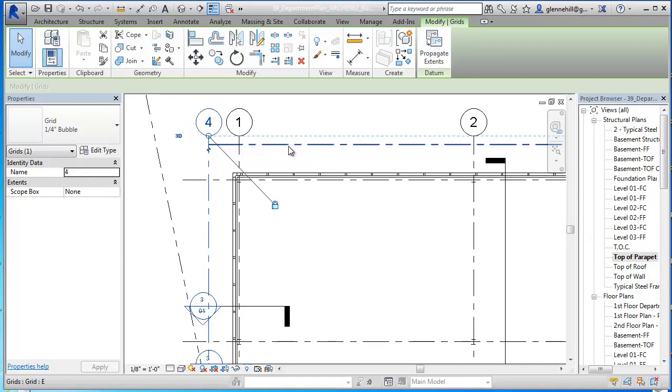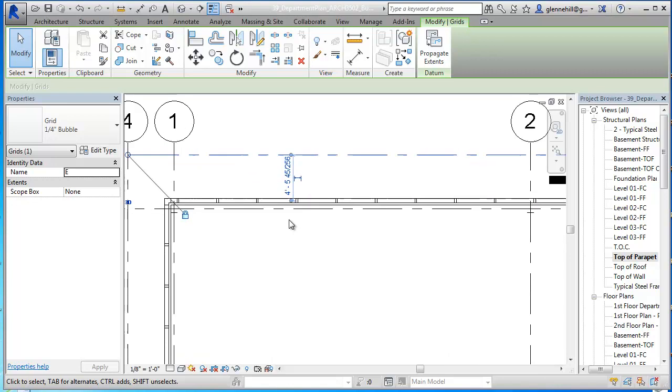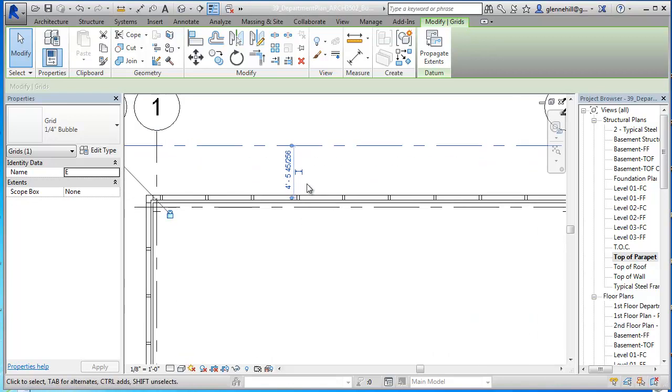And so then I'm going to come in here and establish this distance. Of course, most times when you do these screens, what you want to do is create an area large enough here that people can get in and clean the windows and maybe repair the screen or do things to it. So you don't want it so tight that no one can work in it. Now you could put operable windows in here that allow us to come in and access the screen and the windows for cleaning, but that's much more expensive than just adding 36 inches in here between. So that's what I'm going to do.